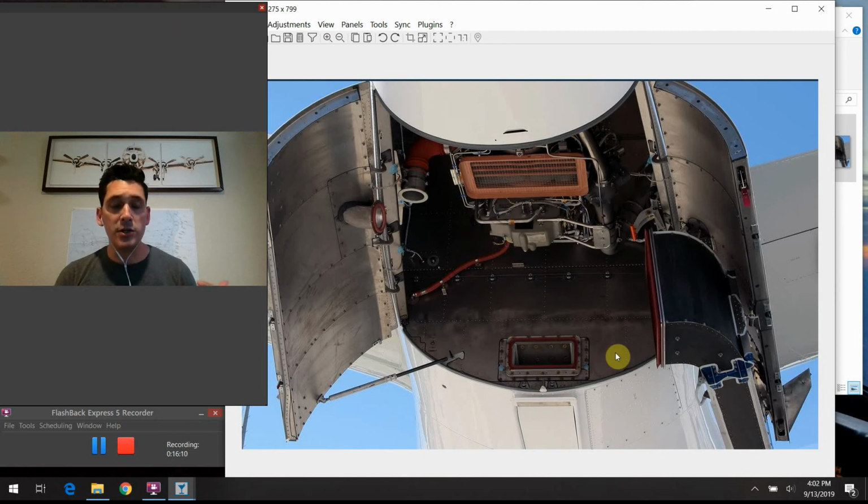system that would shut the APU down if conditions were not normal, or in fact if there was a fire in the APU compartment, the airplane is designed to extinguish the fire on its own without you having to do anything. So it's an interesting thing that Airbus has designed into their system. I think a lot of other aircraft in this present day and age, the new ones anyway, probably have similar workings in their system. But like I said, just that interesting fact about the automatic shutdown nature.